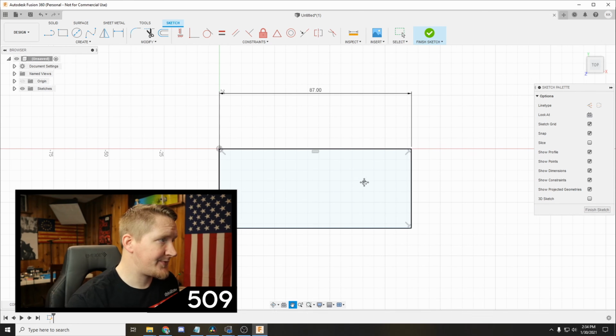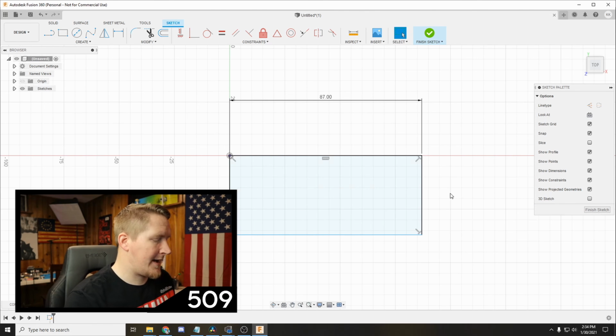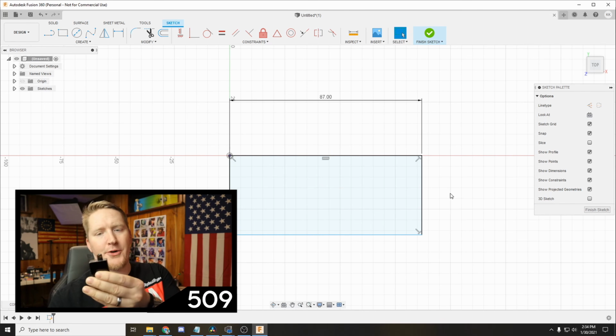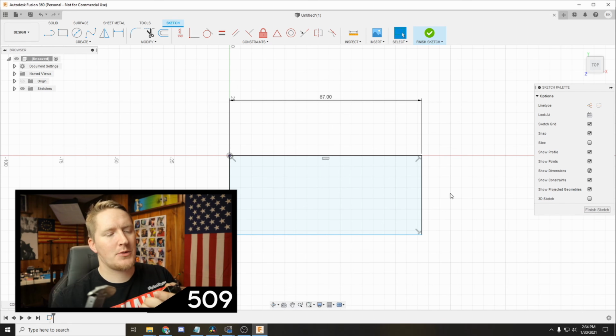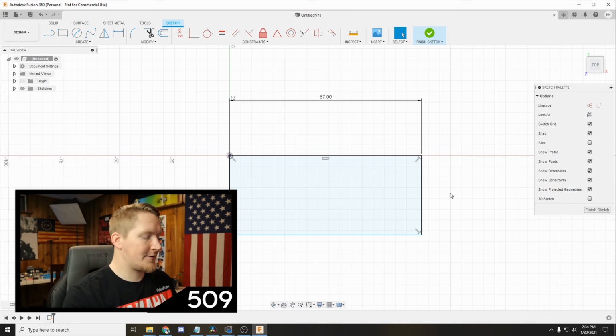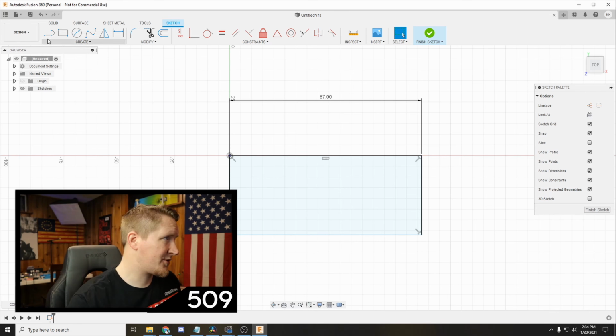So there is the shape of that, and let's say we're going to put the tip on there so we can model that up too. I'm just going to get close measurements. We'll say it's inset off the edge, 12 millimeters to the center of that. So I'm going to create a line from the edges right here and measure down 12 millimeters, just using this as a reference point.